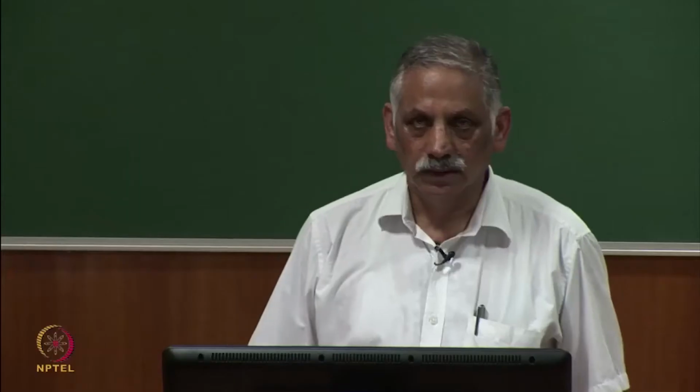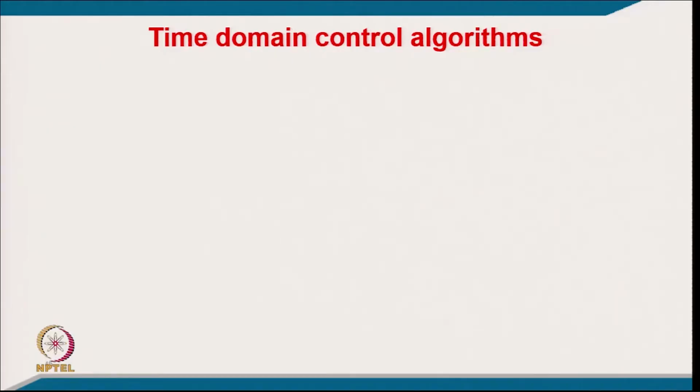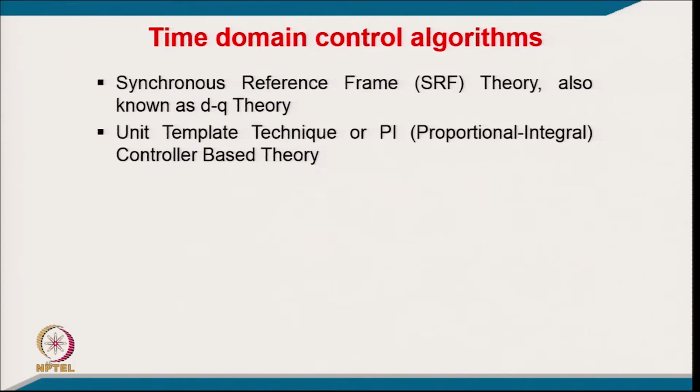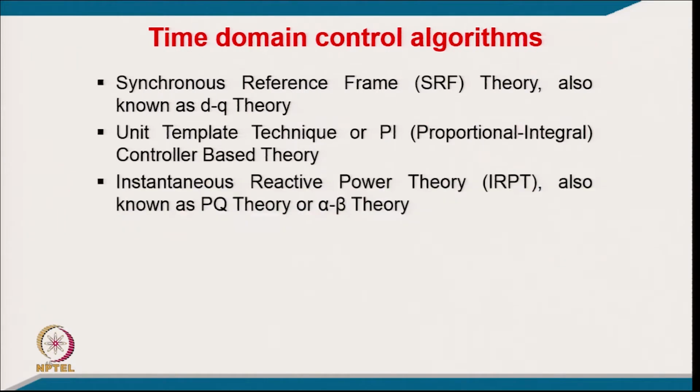Welcome to the course on power quality, and we will like to discuss today control of unified power quality compensators. We have a control technique based on two classifications. One is time domain control algorithms, typically like the famous synchronous reference frame theory, also known as DQ theory. Then unit template or PI controller based theory, then instantaneous reactive power theory, also known as PQ theory